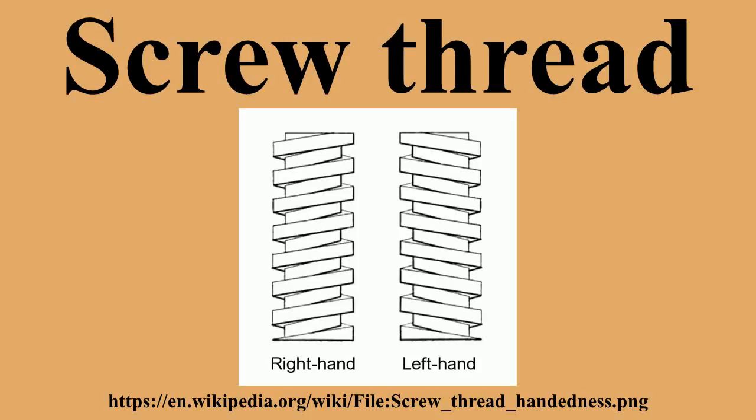In the case of female threads, tap drill charts typically specify sizes that will produce an approximate 75% thread. A 60% thread may be appropriate in cases where high tensile loading will not be expected. In both cases, the pitch diameter is not affected. The balancing of truncation versus thread strength is similar to many engineering decisions involving the strength, weight and cost of material, as well as the cost to machine it.